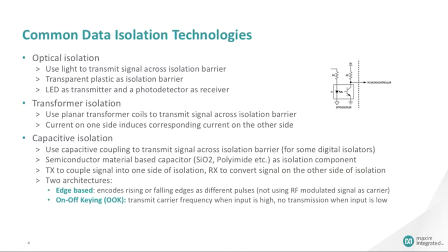There are many different ways to isolate the data. Physical isolation is the most basic form of isolation, which means a physical barrier is placed between inputs and outputs. This can be insulation material, an air gap, or any non-conductive path. However, the signal of interest must cross the isolation barrier. Therefore, we must have a transfer or coupling of signal energy across the isolation barrier.